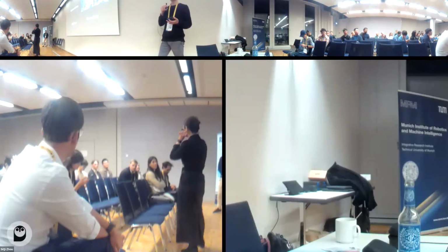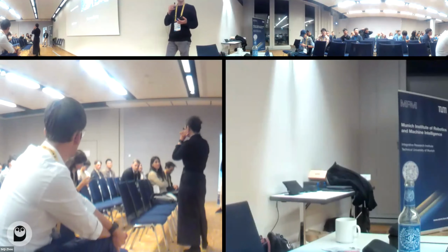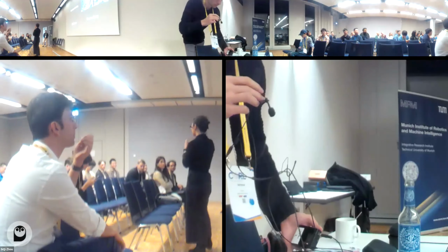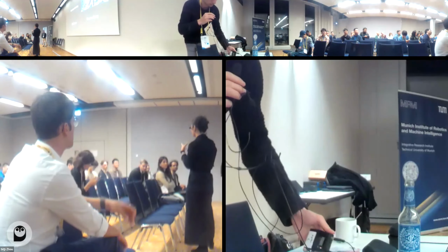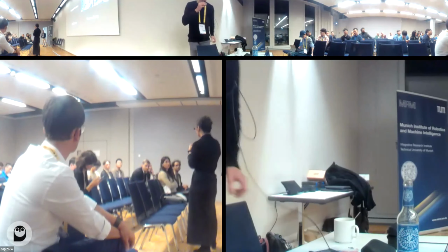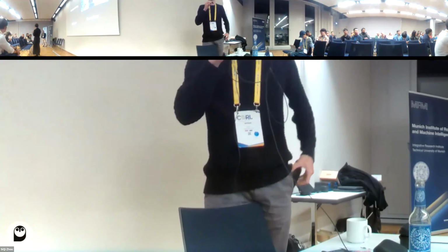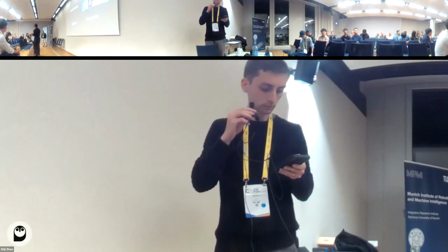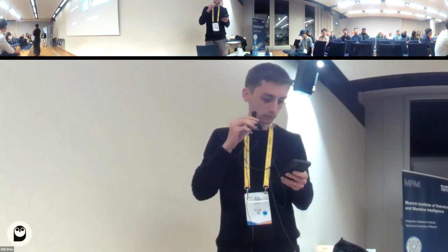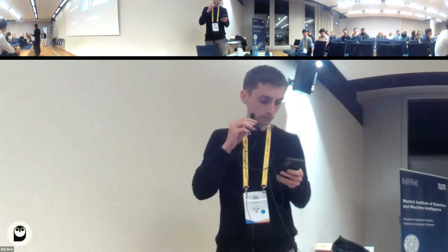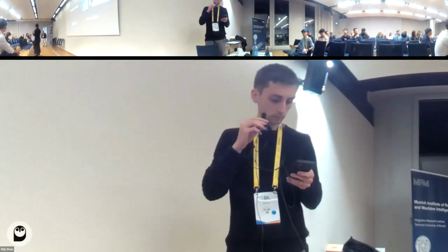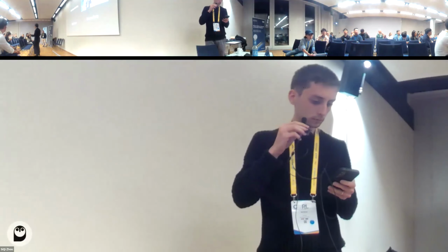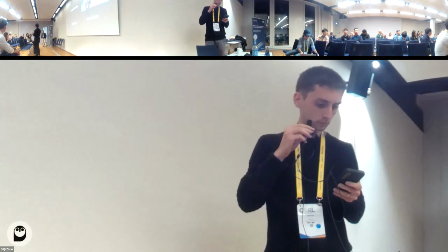I think both are very good questions. Let me go back to the first one. I didn't say that the contact microphone is sufficient. That's why we are still trying to add force sensors. The contact microphone only gives you very high frequency information. It does not give you precise force, and also does not give you low frequency force information. So I think the contact microphone is a very convenient way to get a little bit of tactile, but definitely not the best way. If you can design your own tactile sensor, then go for it. I think that's still valuable.